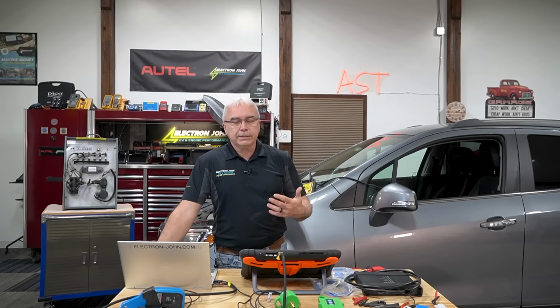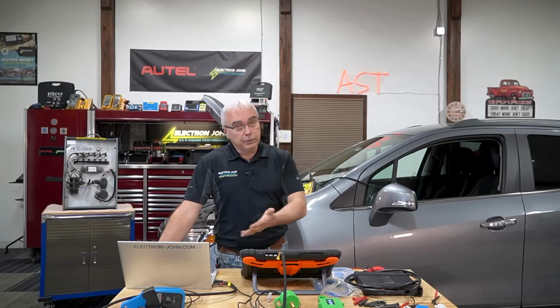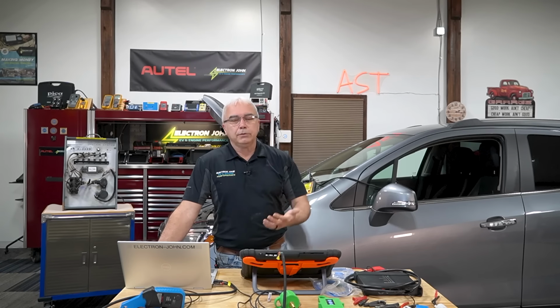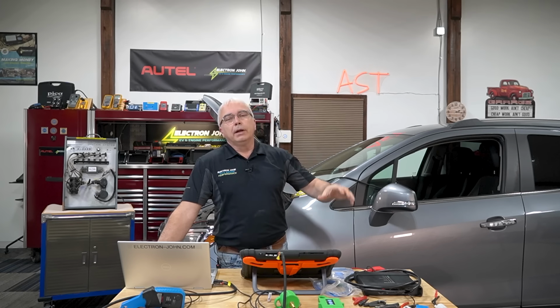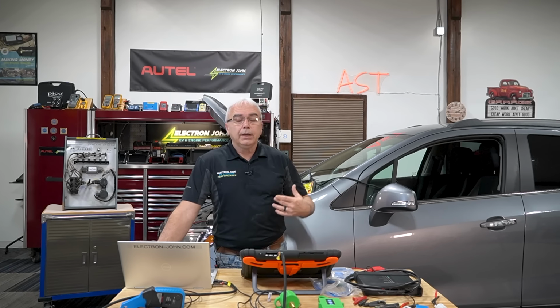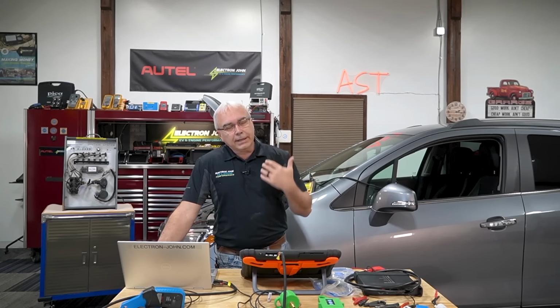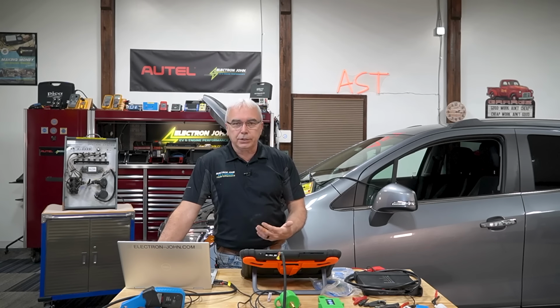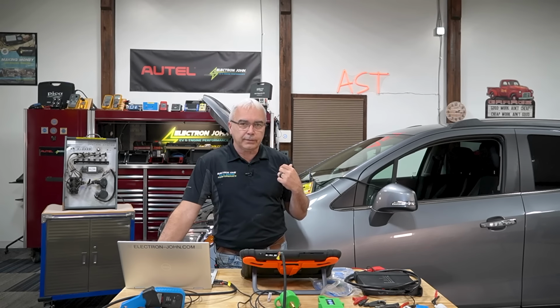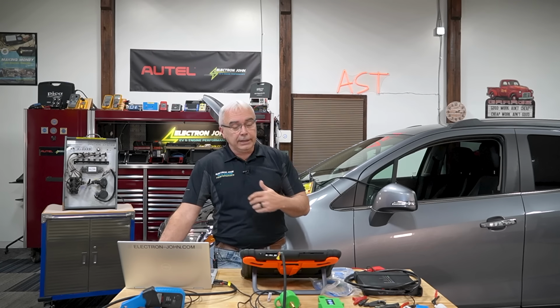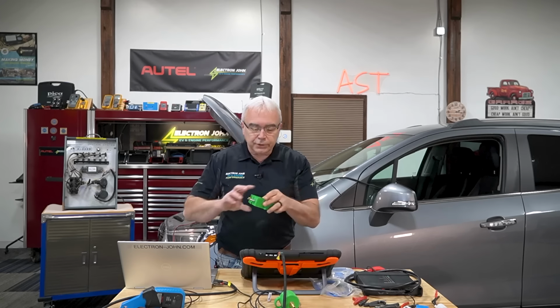Now, those series of tests in my head, if it was a breathing type of scenario, maybe I want to do a compression test, a cylinder leakage test, whatever the case happens to be. I'm going to come around and open up the hood. Now, my diagnostic path may change depending on how hard it is to do some of these tests. So maybe one of the tests I wanted to do for that scenario would have been an in-cylinder pressure transducer test, right?